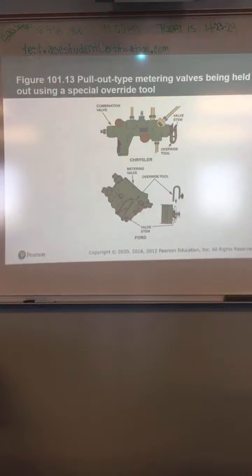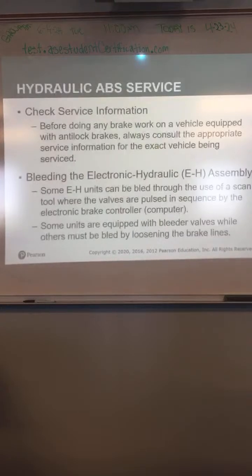A metering valve can be a press in or a pull out type, by the way. Special tools for each one. That's only if you're going to pressure bleed the system and only if it has a metering valve, okay? I seriously doubt you'll do either one of those.